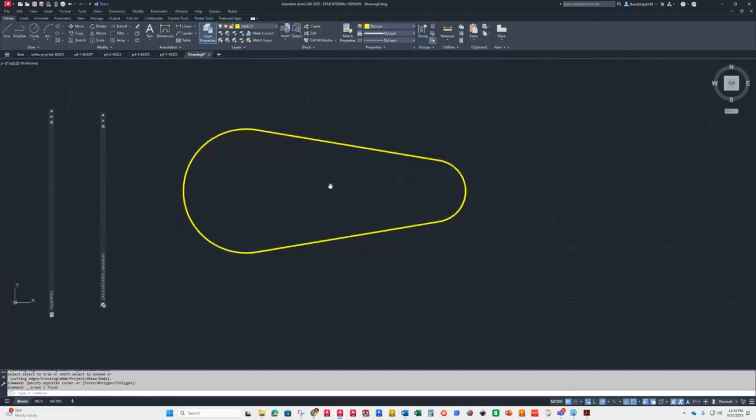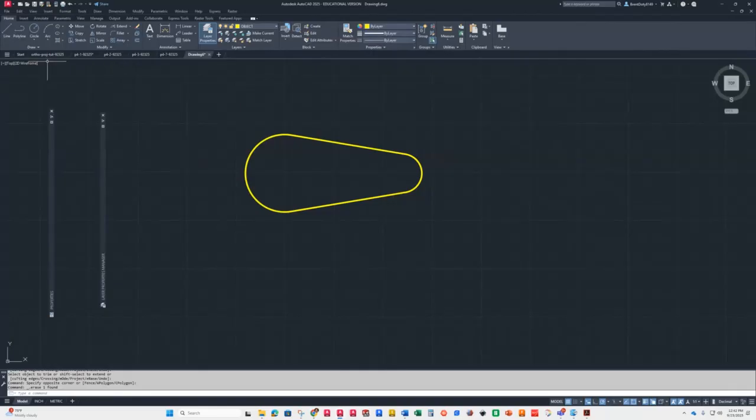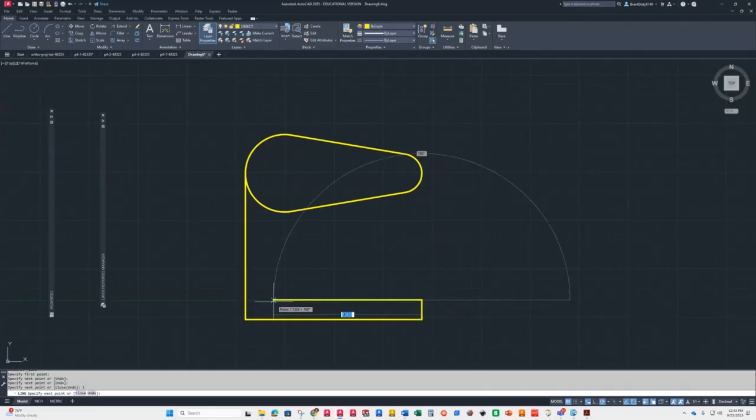Okay, so I've got the base shape right here. Then I could come down here to the bottom and draw a line from here down and come over. And if I wanted to, I could highlight here in the middle of this, bring it down. Or if I did the math, I could say it's 9. I know it's 9. And then the thickness for that base is 1, so I could go up 1 and then draw it back over to here, like so. And I'm just going to trim that off. All right, so there's the base, there's the front view, here's the top view.